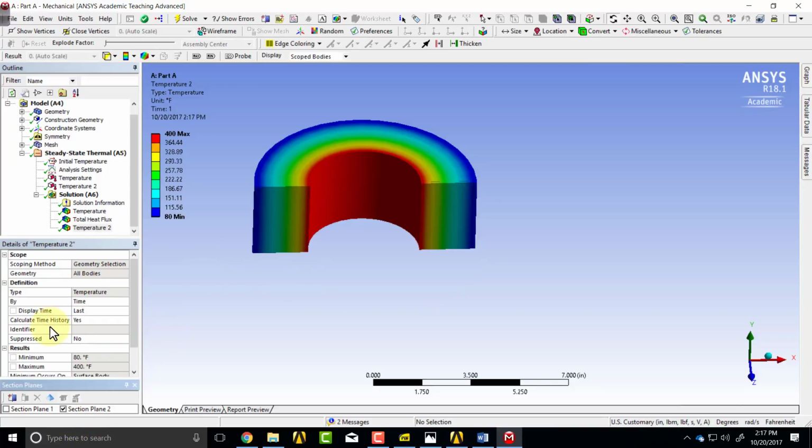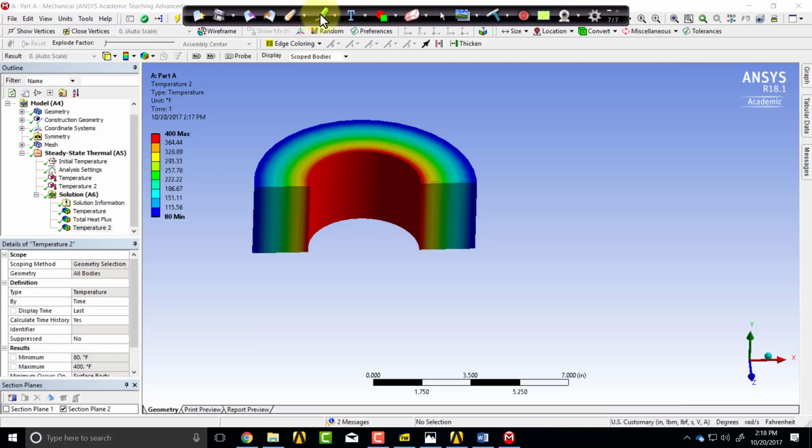And if I take a section through that particular model, and I focus on this particular section, okay? And here you can see there's only variation in the radial direction. There's no variation in the axial direction, but we will have to have the axial direction also in there, but don't need to resolve it with more than one division along here. We'll see that later.